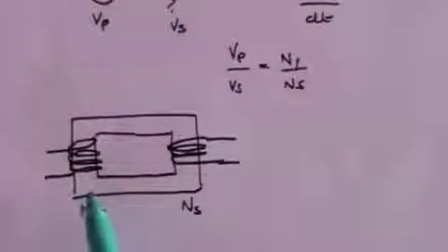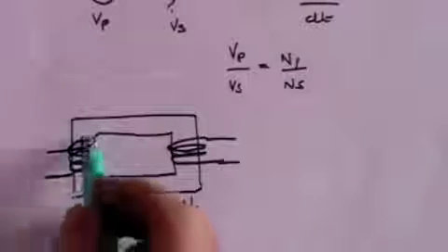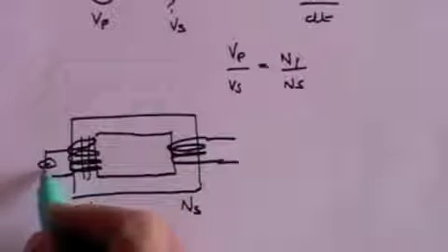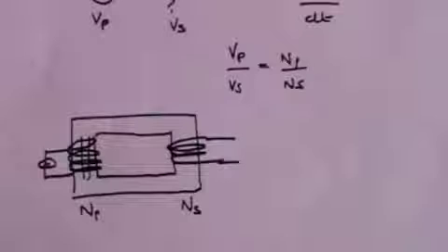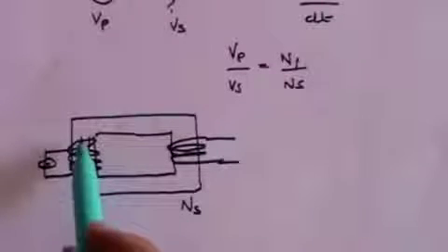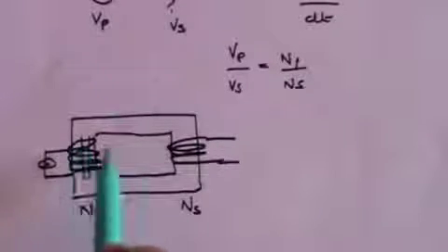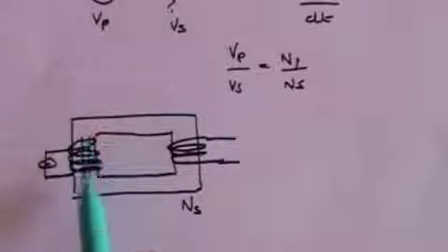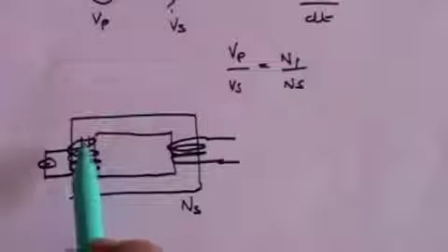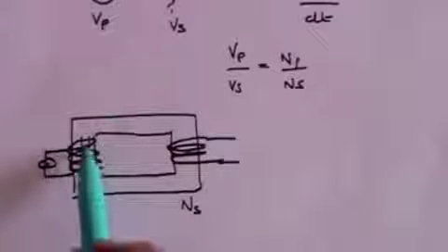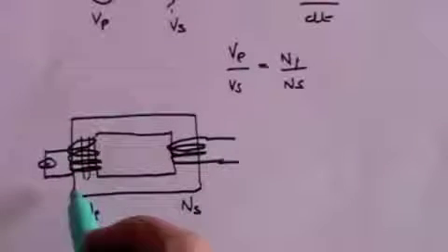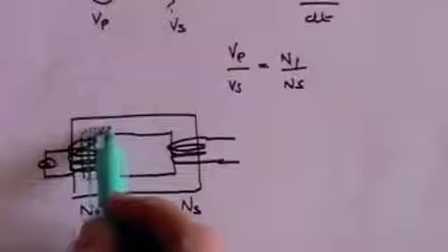But why does this work? Well, what happens is that you get a magnetic field in the primary, because this has got an alternating current, alternating voltage attached to it. Once you have a magnetic field in the primary, then that magnetic field will magnetize the iron core. And once the atoms in the iron core inside the solenoid are magnetized, then they will have a magnetic effect on all the atoms right the way around.